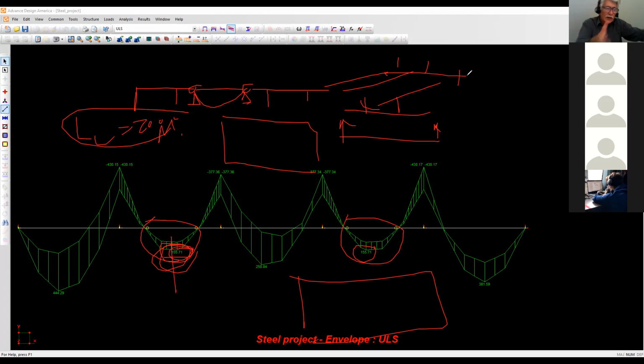Therefore, the LU is that spacing in between those members, and that's my LU. Now I've got my LU and my MF, so I go to the beam selection tables and find a beam. Don't worry about the IX, don't worry about the VF, because you can check your VF while you're there, and I'm sure it's going to work. And when it comes to deflections, you don't worry about it.